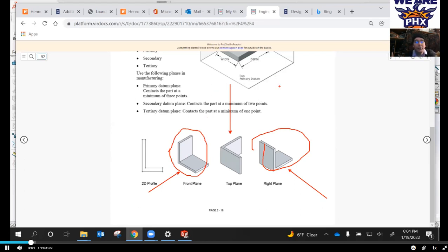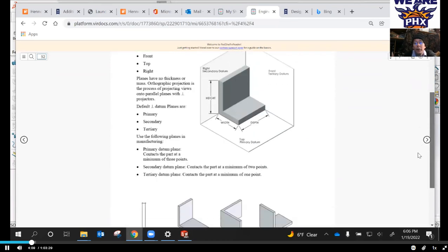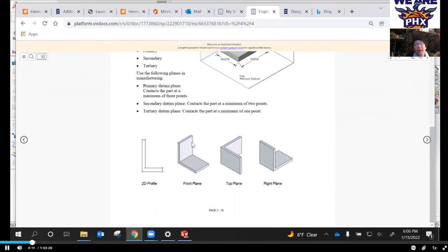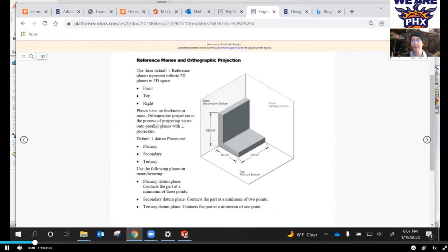And I kind of stress this because when you're creating a file at work, and it's a part that goes into an assembly, and the design of the assembly is such that it would be really easy for future parts and for the current part as you put it into the assembly, you want it to be oriented like this. If it's modeled like this instead, you'll have to change stuff. You may just end up modifying the part to make it look like this, so that it all fits together the way that's design intent. So things fit together the way they are intended.